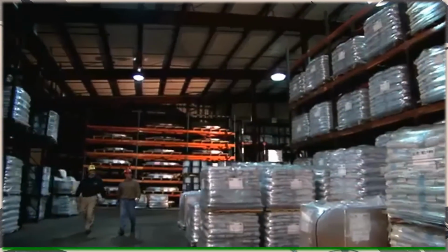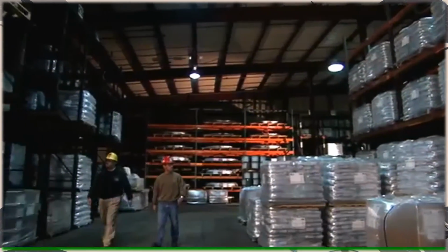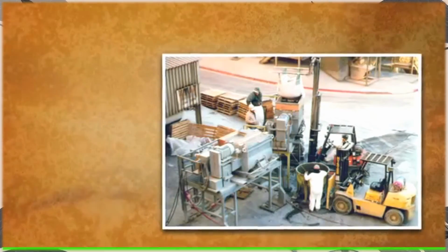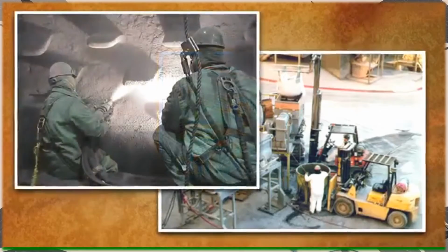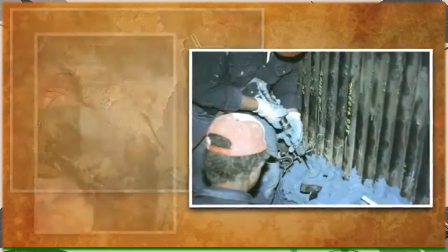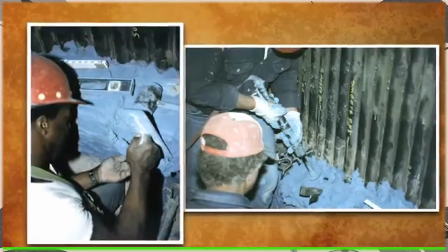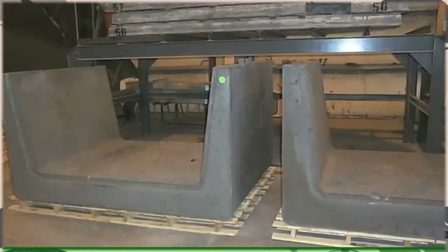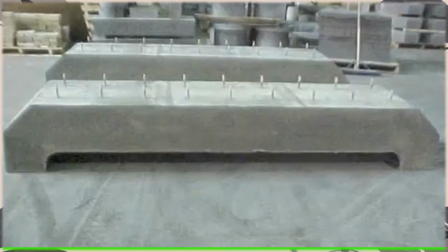Some are packaged very much like concrete mix you might find in a hardware store. Monolithic refractories may be poured or pumped into place, sprayed onto surfaces, rammed, or applied with trowels or other tools. They can be precast into predetermined shapes, providing additional flexibility in application and use.